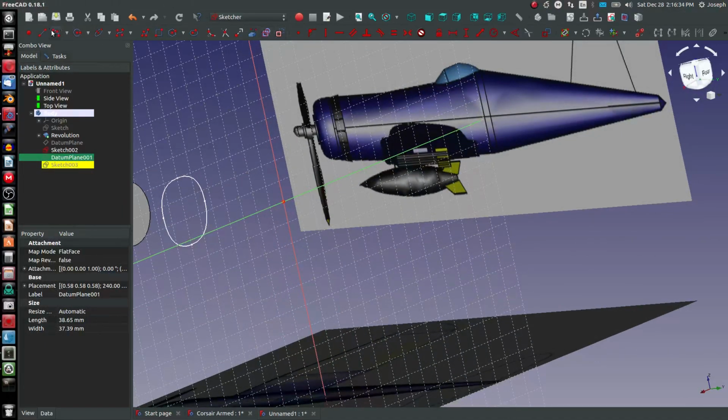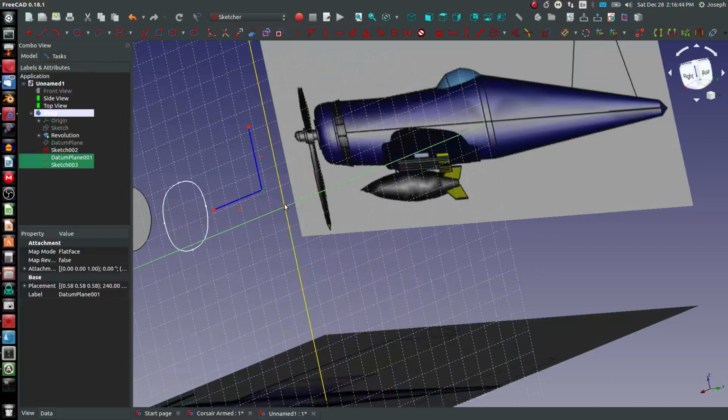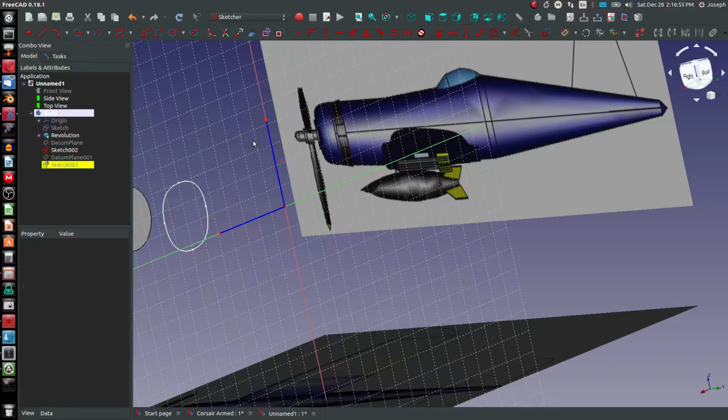I'm going to do roughly the same thing, Polyline in construction geometry, create a vertical and a horizontal line, and I can manually, that's my mouse again, this is the mouse that I normally use, I can manually make that go onto my origin there.